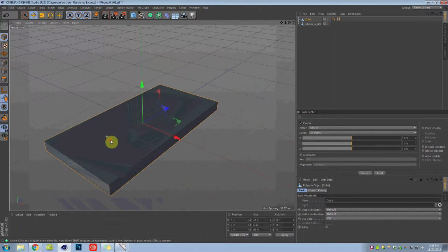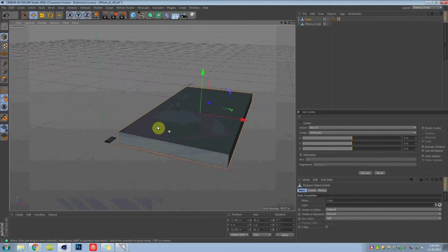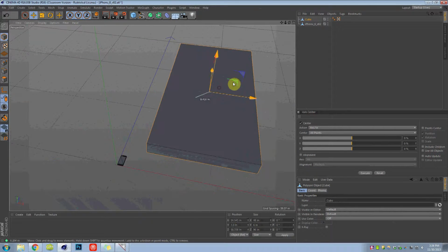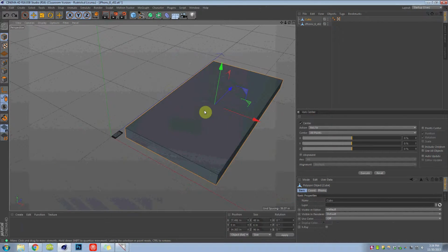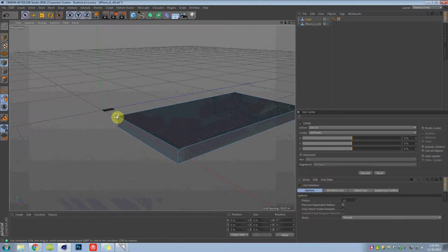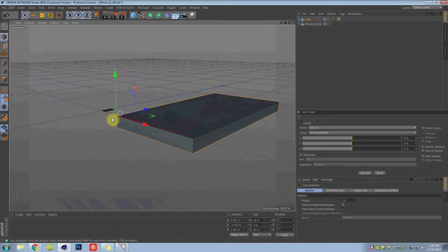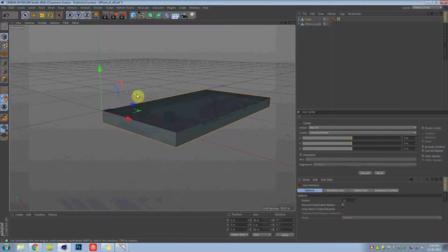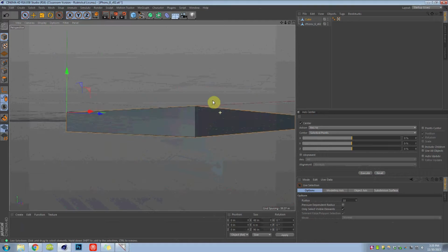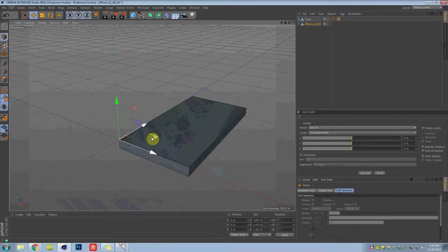And I need the stock to exist in the positive quadrant in terms of X and Z in Cinema 4D, meaning when I move it, its location is all positive, and then it needs to be in the negative Y. So this corner, indicated here, selecting this point, making that my axis center, that point needs to be at 0, 0, 0 position. I positioned it at 0, 0, 0, so the stock itself is below the work plane, but in the positive quadrant.